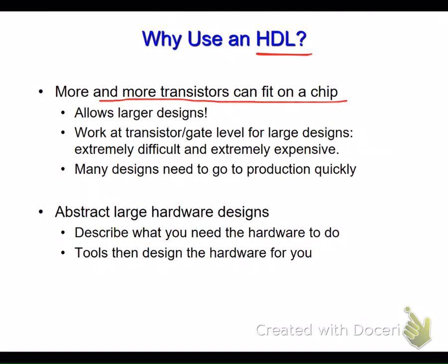However, if you wrote your design in Verilog or VHDL, it will be easily transferable. You can just get your code, go to that tool, run it on Altera, and then take exactly the same code, go to Xilinx, which is Vivado in your case, and run it. So it will be easily transferable. Okay?